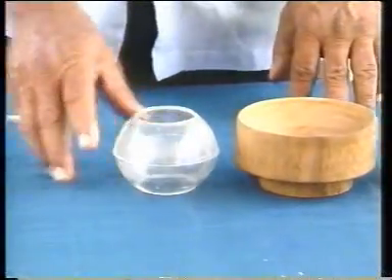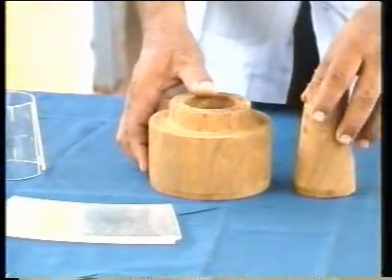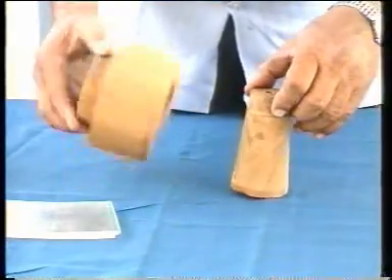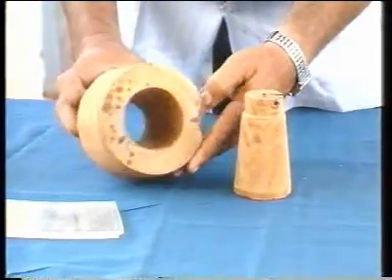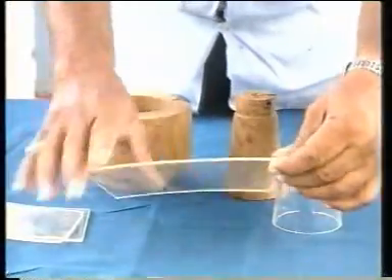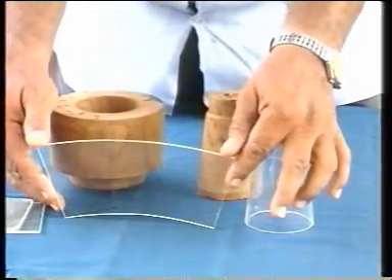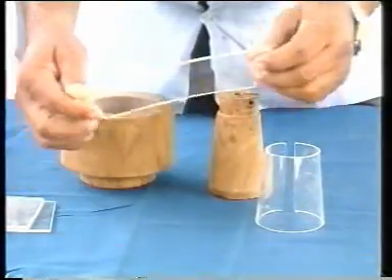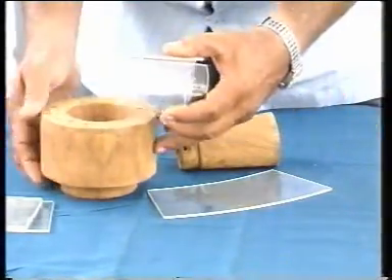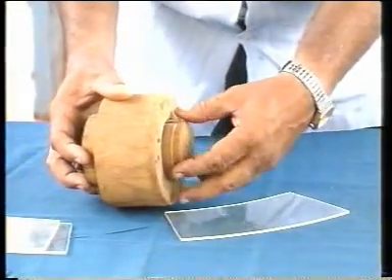Then the second, the taper part, we made similar type of male and female die. You can see. And to make this taper part, we just cut from it, making a template, and we cut a perspex again, heat up, and formed almost the similar type, formed here, and we got the taper part.